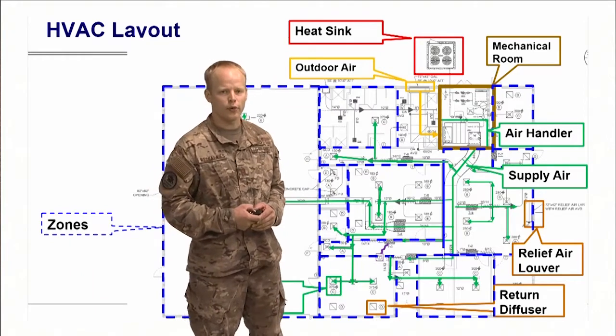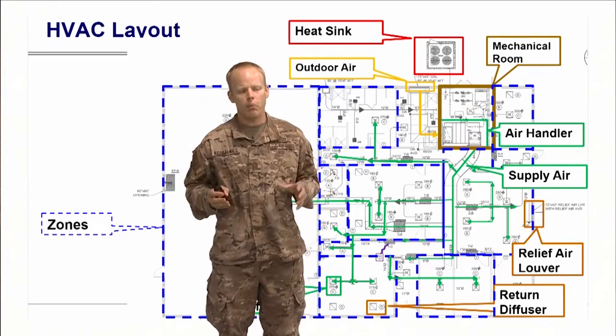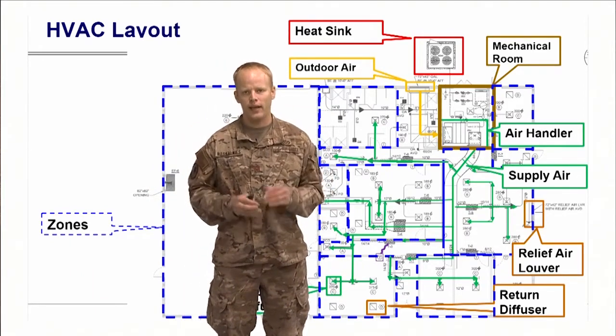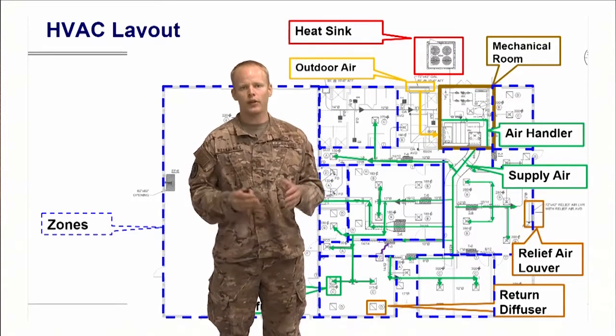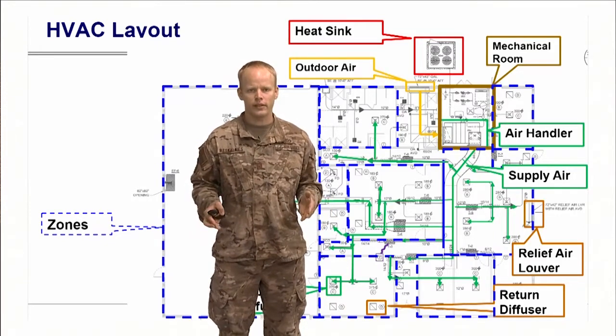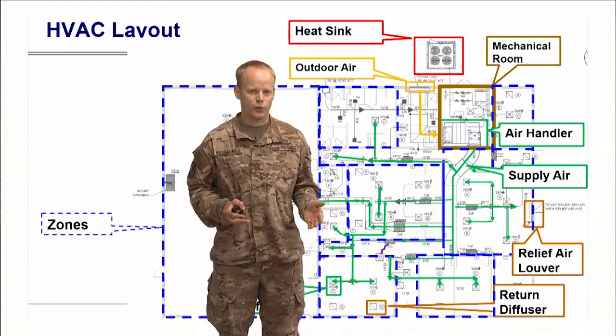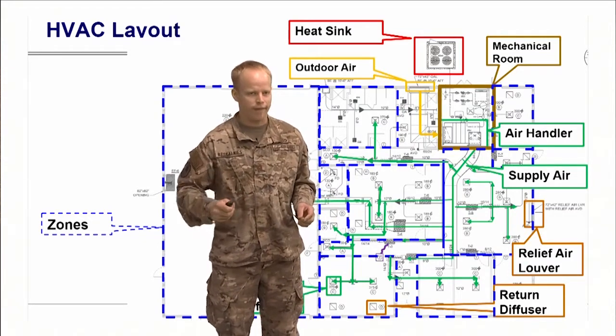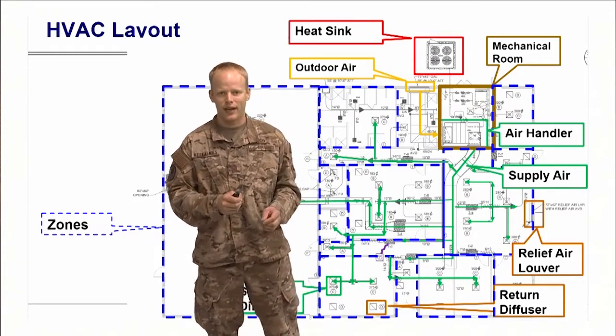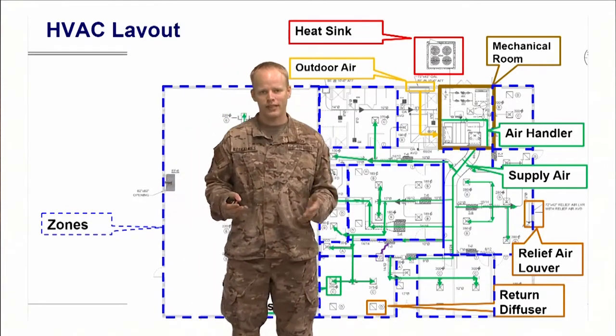They're spread out through each zone because when we push air from the outside in and we condition it, if we don't let it escape, we're going to pressurize our building. You know when a building's been overpressurized when you open a door and it flies open really, really fast. The building's probably pressurized.